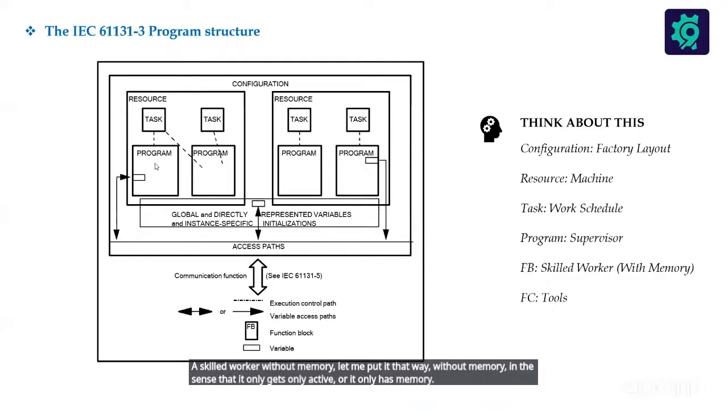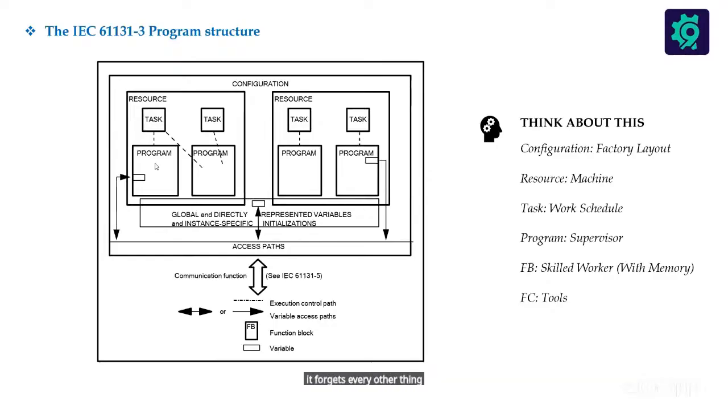It can only keep track of the data while that particular FC is on. Once it is done, it forgets everything it has. So it doesn't have a storage where the activities that went on with it are stored. So it simply means that if you are writing a program that needs its variables and values to be stored in a particular memory, maybe for a particular use, then it is important that you know that you are going to be going with FB.